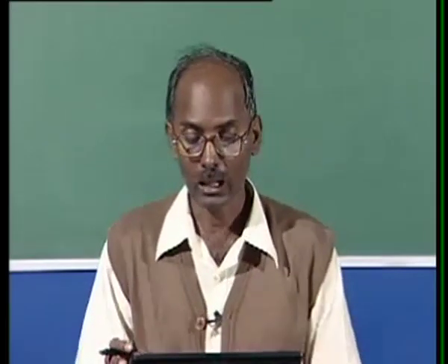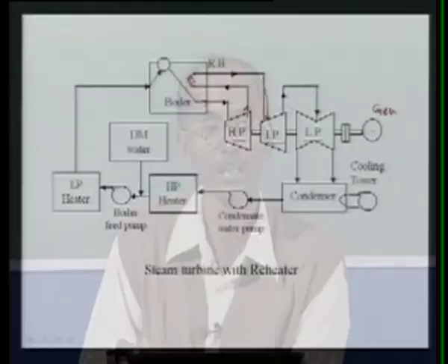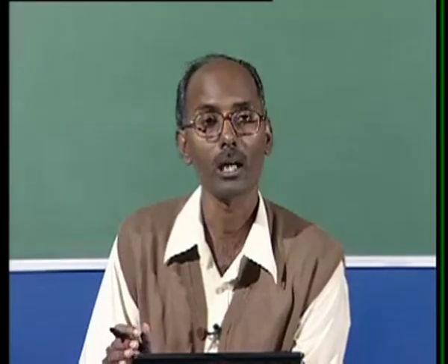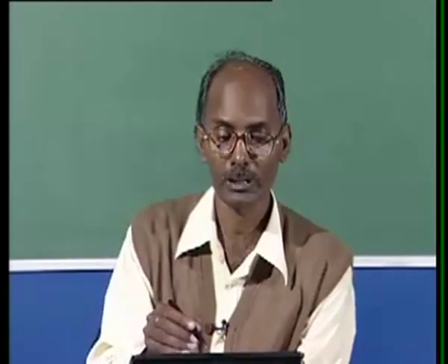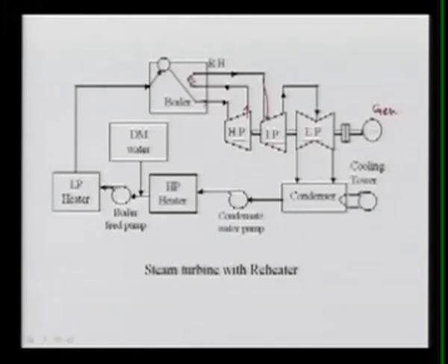Again here I want to mention that the output of this HP turbine is reheated, because the energy consumed in HP is very, very high, and then the steam which is coming out from the HP turbine is having low pressure and thus low temperature as well. If it is not reheated, there will be a possibility that this steam will be converted to water, and that will damage the blade and the efficiency will be poor.